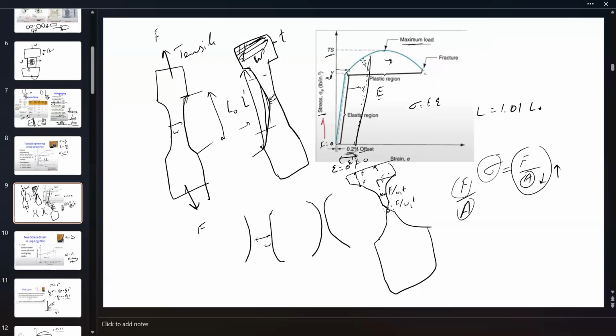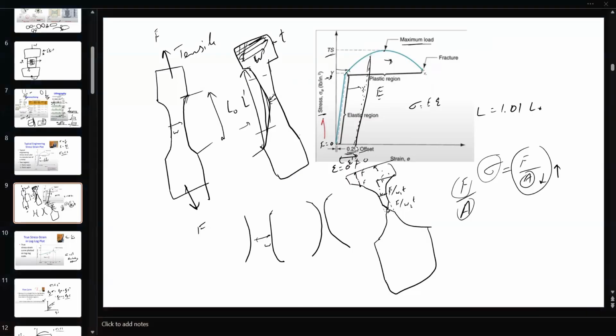So at whatever point in the plastic region, this is the plastic region, you remove the stress, it will come back, not to the original length, but it will shrink back to some length. And the slope of this path taken is the same as this initial slope actually. The slope never changes, just there's some residual stress strain remaining inside the sample once you remove the load.